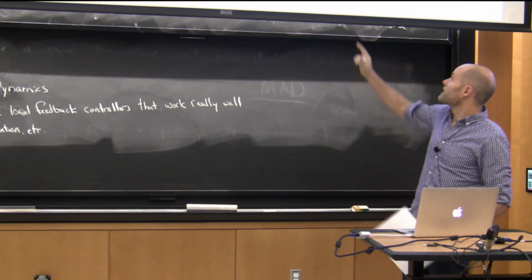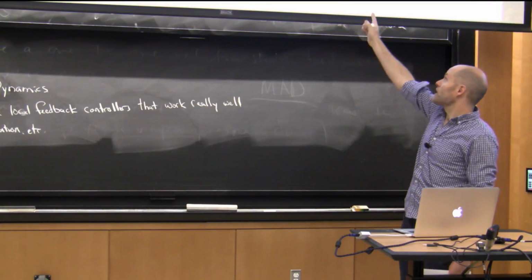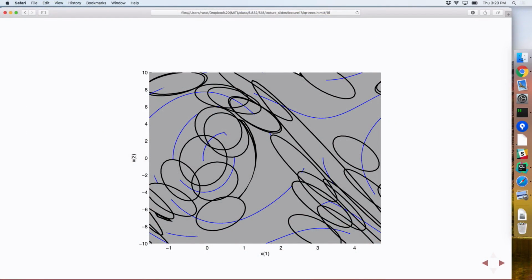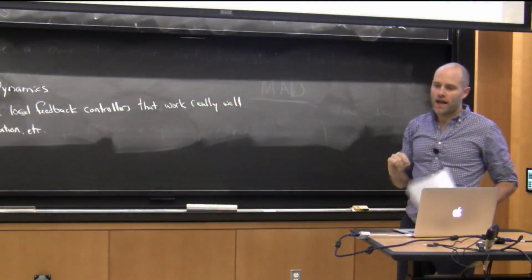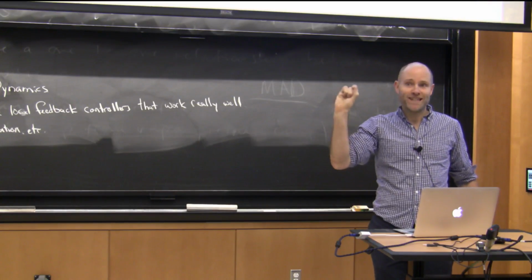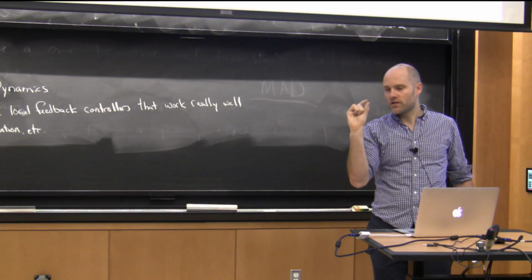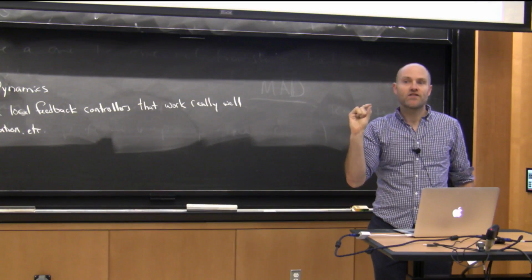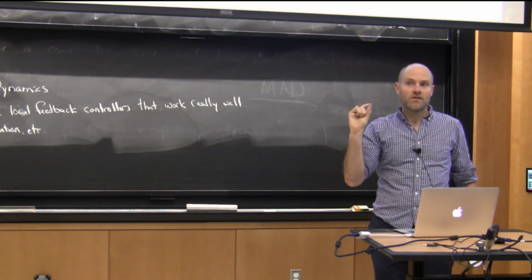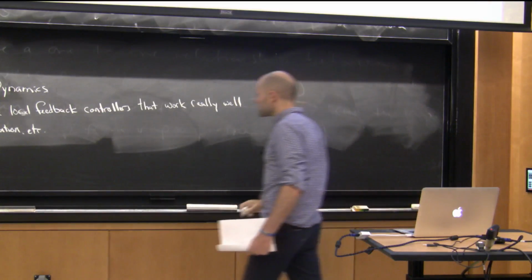That is no longer true here because my samples will always be outside some funnel, okay? So the trajectory optimization has to get from some point over some non-trivial distance to touch back to the tree. But you can write your trajectory optimization as minimizing the cost function over time, subject to a final tree constraint, okay? So you say the constraint on the final state is that it is touching one of the nodes of that tree. That's not a differentiable constraint, because as it moves between